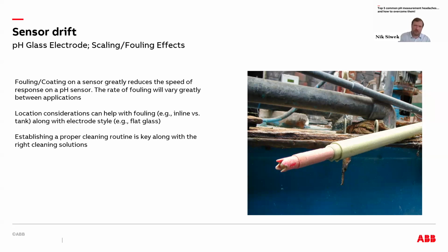And then worst case scenario, if you are prone to really high solids and high buildup, auto clean options are always a great way to minimize the time you actually go into these sensors. They'll help automatically clean the sensor periodically throughout the day for you.